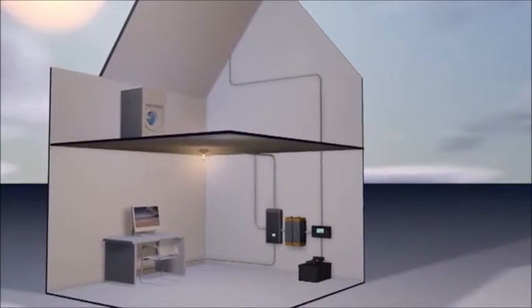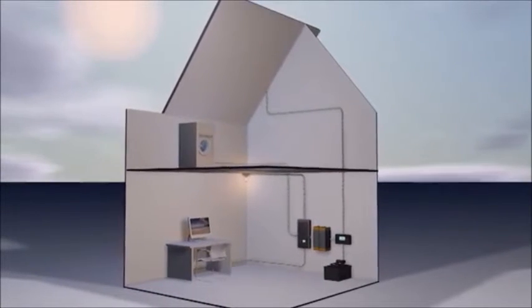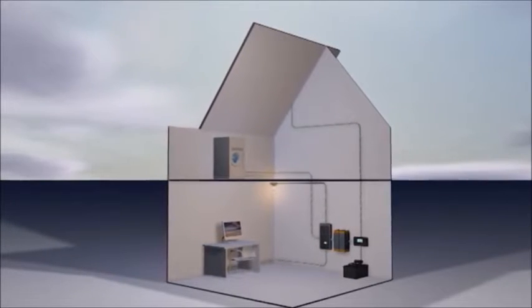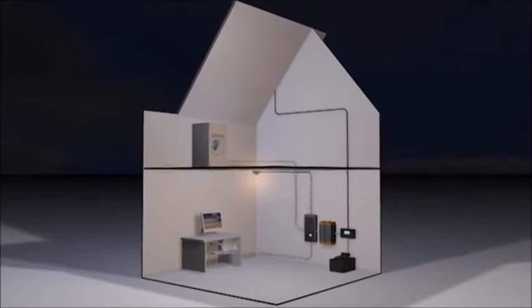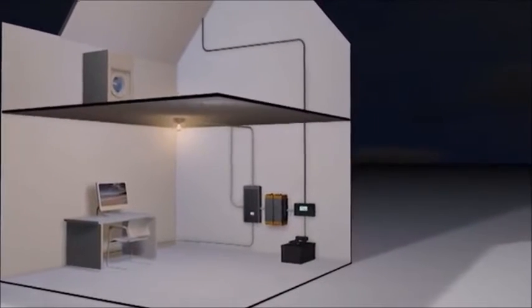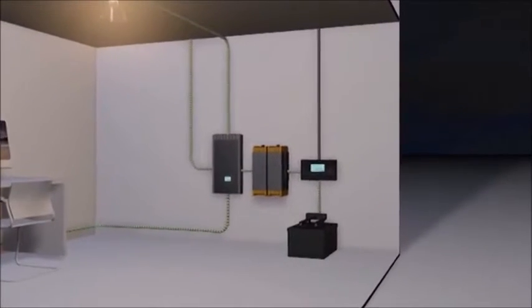The system is designed and sized such that during the day, with the sun shining, the system generates enough power to at least meet the load demand for the rest of the day. Therefore, the PV system acts such that the battery is net charged over the day. After daylight, the rest of the power demand is fulfilled by the battery.